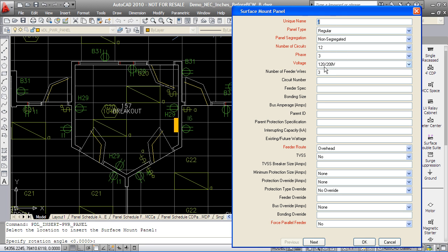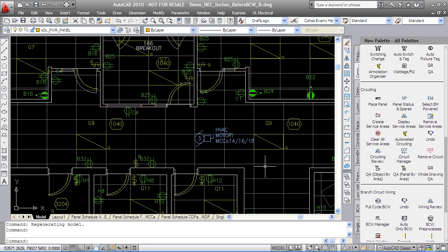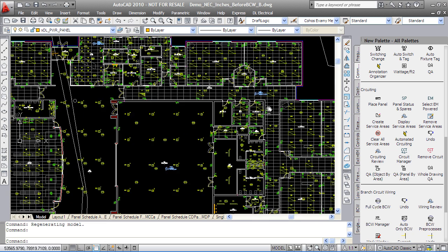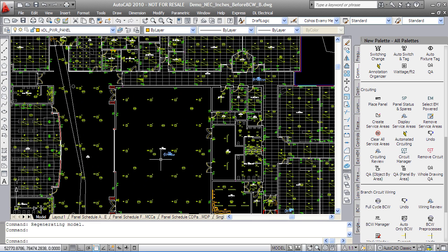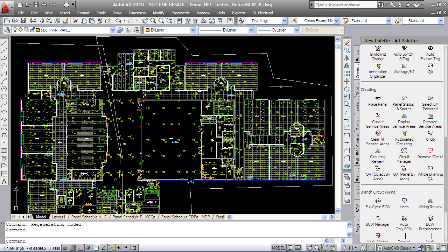So since this panel won't have any load today, we're going to give it a presumed future load of 100 kilowatts, and then we just need to circuit it. So now you can see we've assigned a circuit to our new motor I. This motor and the motor that we changed the horsepower on will have their protection and feeder calculated next time we run a suitable report.